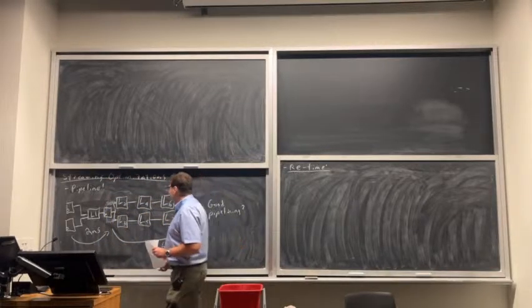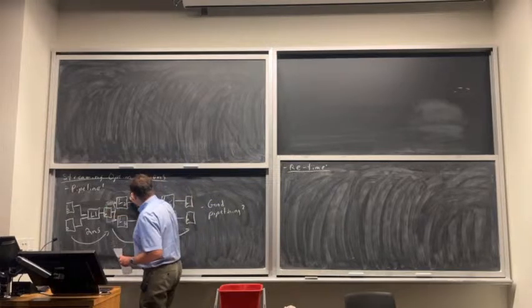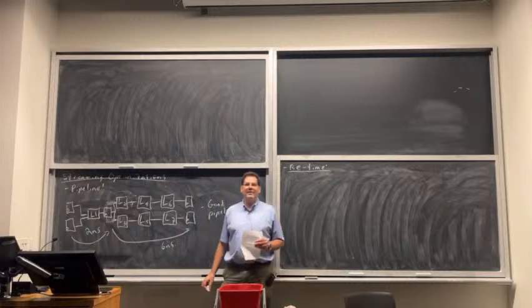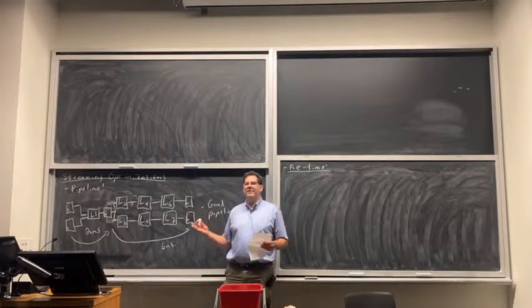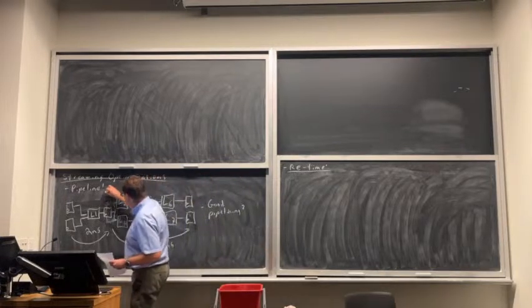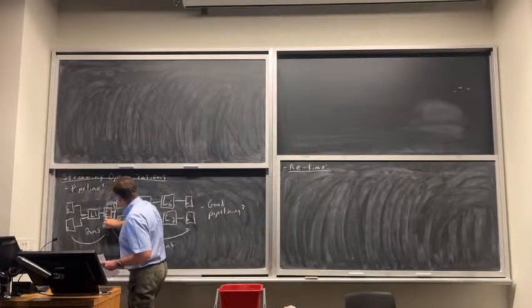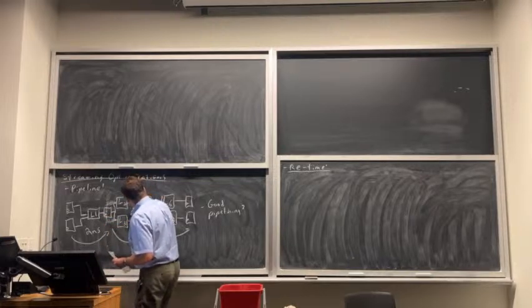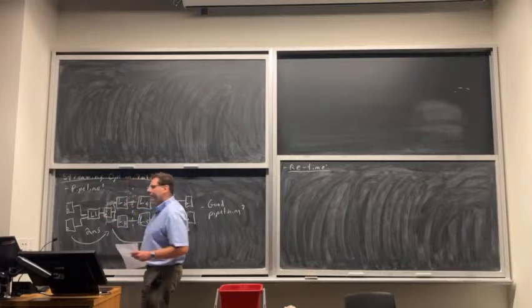Can I just move this register to this spot, like this one spot? Is that good? What do you think? No, you can't do that. It's basically you're moving a cut line. So I had a cut line here, and I could move the cut line to there. So what that means is if I move this register from here, I've got to move it to all the fan-outs.